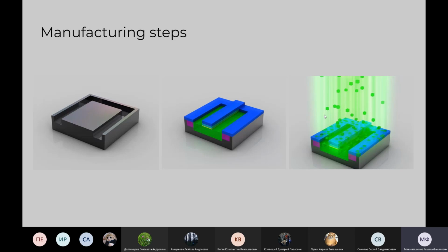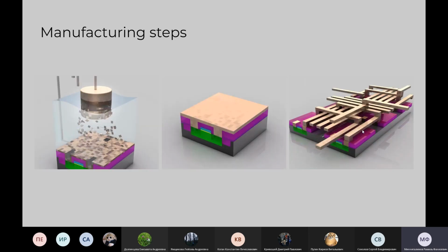Through a process called ion implantation, some form of doping process, the wafer exposures are etched with ions. The ions that are implanted in the wafer will change the way silicon in these areas behaves. The wafers are fed into copper sulfate. At this stage, copper ions are deposited into the transistor through a process called electroplating. Copper ions travel from the anode to the cathode.